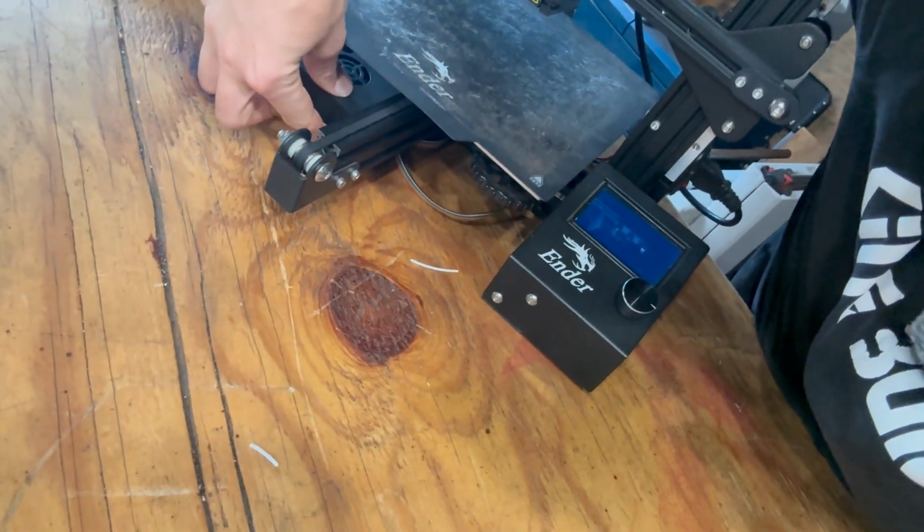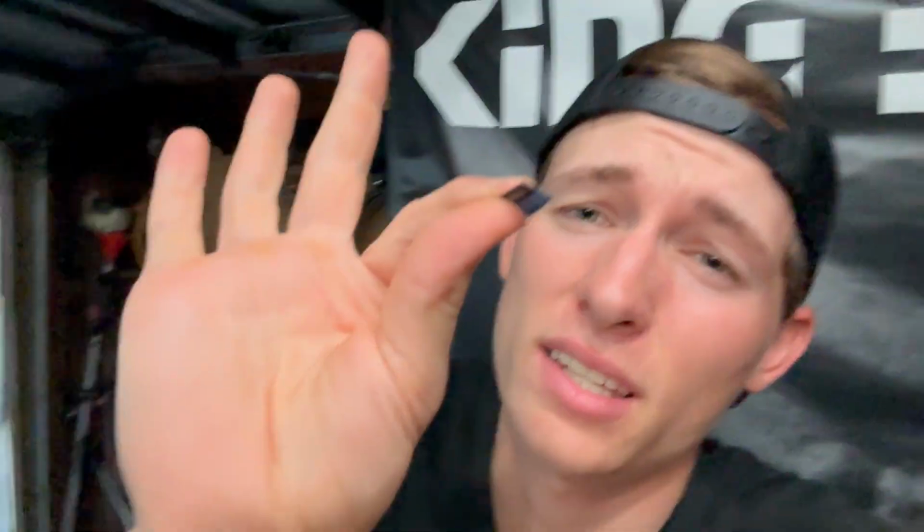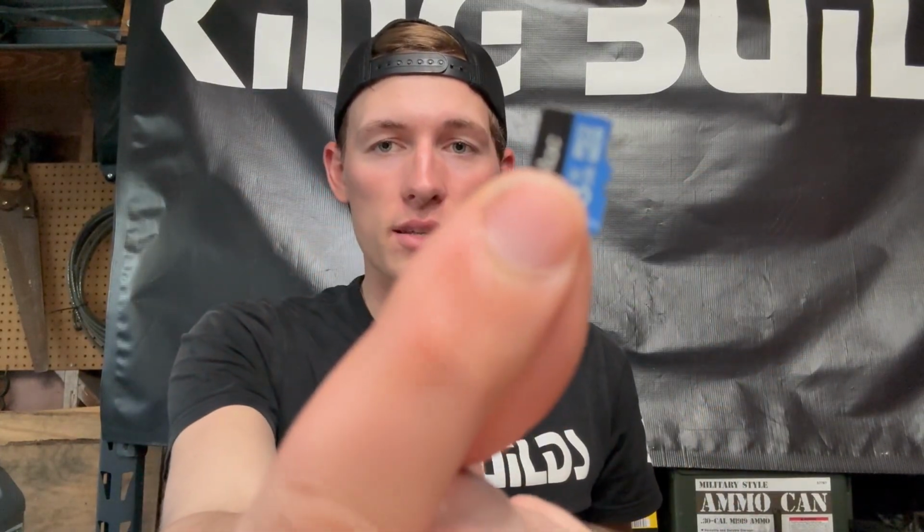3D printer. Okay, so for the Creality Ender 3 Pro, once we have our design, we are going to take out the SD card, which is right in the front here. Click, let go, and it pops out. This right here is a little SD card. You're gonna put it into your computer, and you're gonna take that G-code file and you're gonna drop it onto this SD card. You'll be able to print it onto your 3D printer.